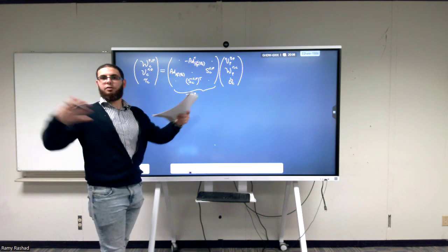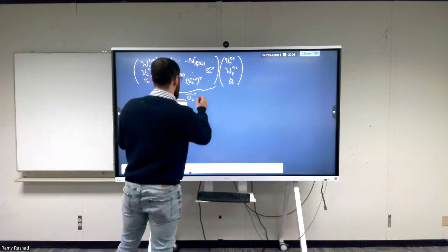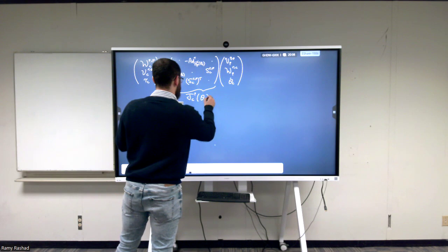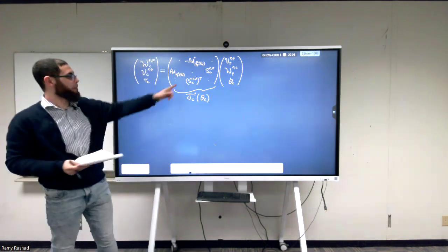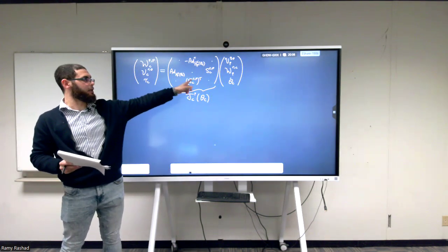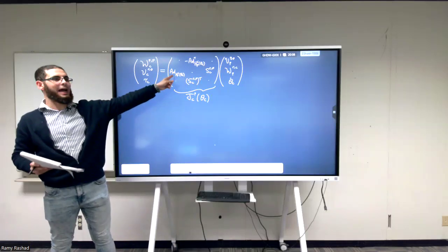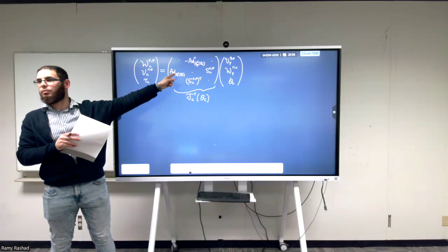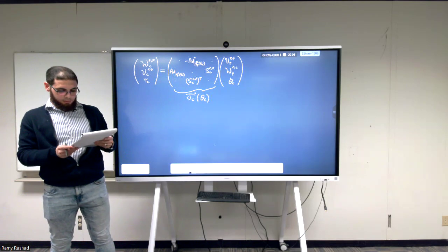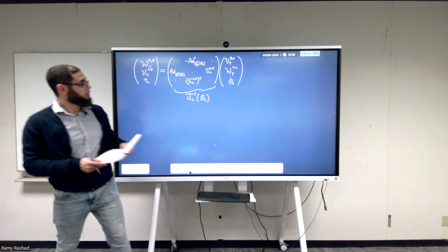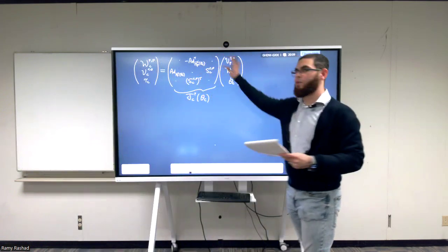It's just one big transformation that is only a function of theta C, and it takes as constant parameters the SCCP, because the H here I calculated with the exponential map. And that's it. This is everything the joint does.